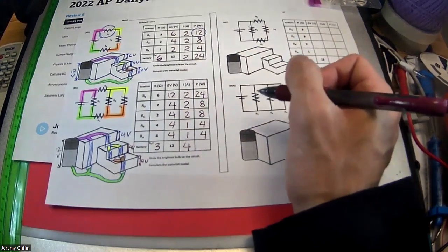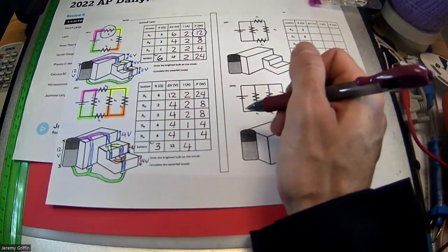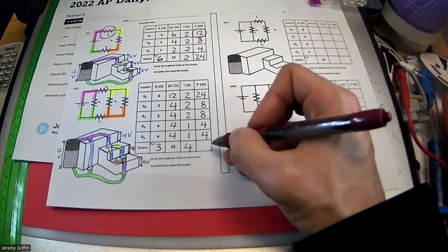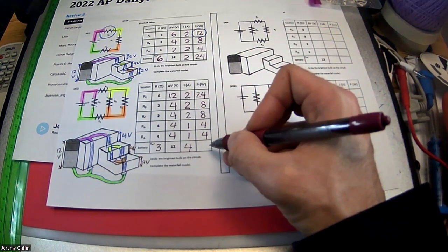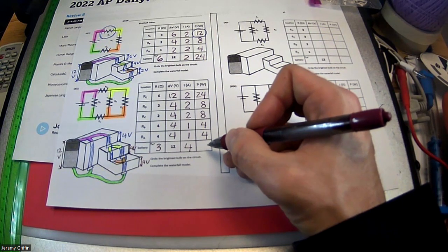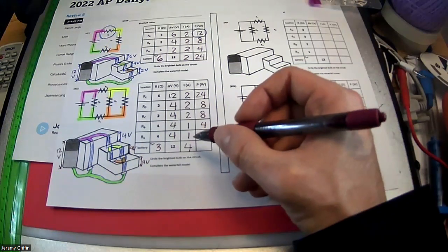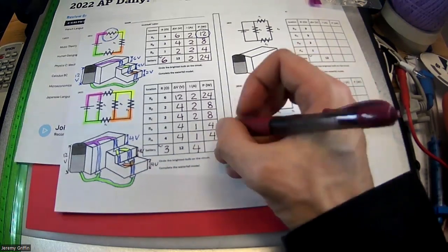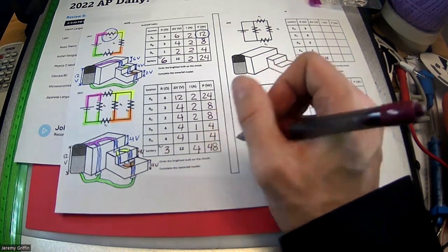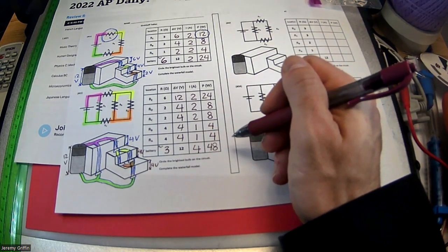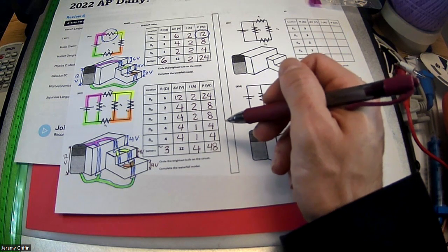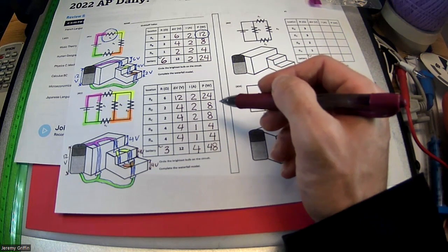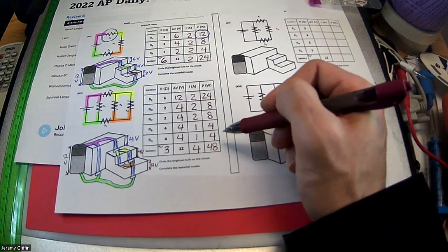Right? Now pause right here because I'm right at the end of this table. Okay, I hope I got everything right. Remember, I told you guys 2 perspectives for this very last cell. This very last cell tells you the power supplied by the battery. Now, the power supplied by the battery, you could go I times V at the point of the battery, so let's do that. 12 times 4, that'd be 48 watts. That 48 watts also better meet the electricity demand from each of the resistors. So if you add up all the watts from each resistor, it has to add up to 48. Let's see if it does.